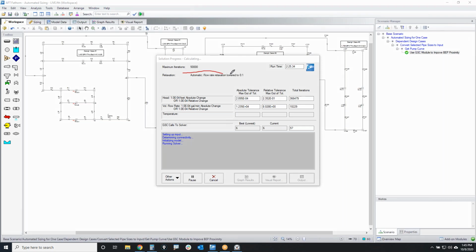And as you can see, what it's also doing for just about each iteration, it's adding relaxation, so that way it takes smaller steps, one iteration to the next, as it's trying to bounce around on the curves with the Newton-Raphson method as well. Imagine trying to do this by hand. It would take a lot more time and be a lot more difficult.